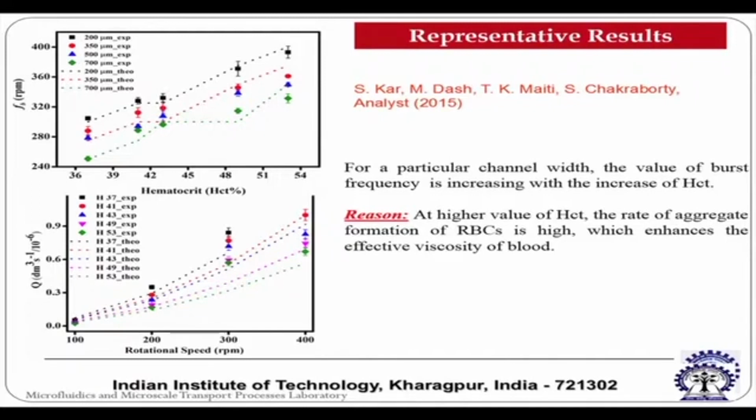So the burst frequency of the CD based microfluidic platform can be taken as an indicator of the rheological aspects of the blood sample, and this rheological aspect may in turn be related to certain diseased conditions. Therefore by directly reading the burst frequency one may possibly think of the existence of a particular diseased condition in a blood sample.